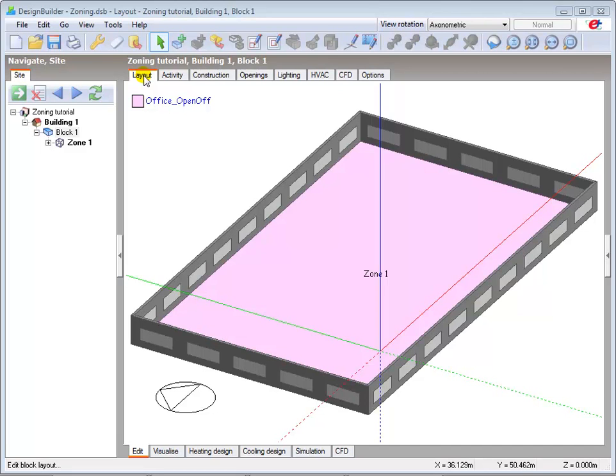They have no thermal mass and present no barrier to heat and airflow depending on the natural ventilation options set, which will be discussed in a later tutorial. Virtual partitions are commonly used to separate open plan areas which have different HVAC or lighting systems. They are also used to model the localized effects of solar gain and daylighting in perimeter zones, typically by placing the virtual partition 6 meters from the glazed facade.